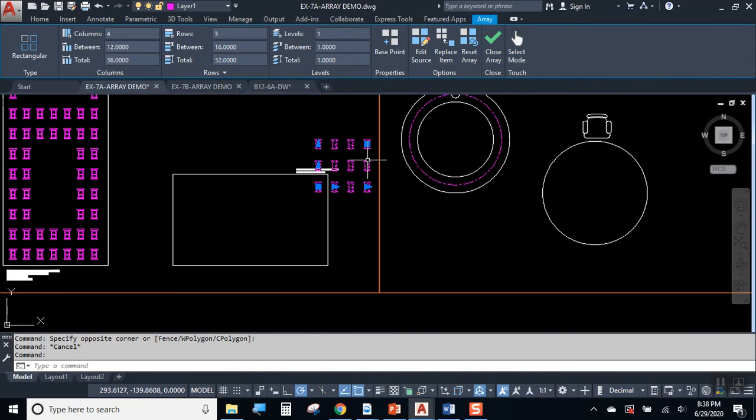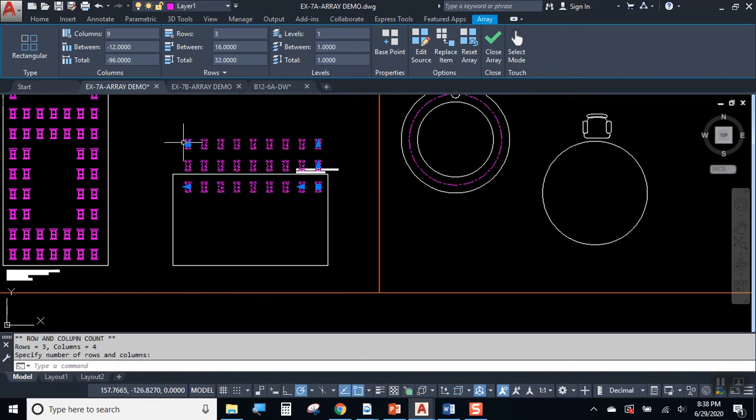Well, part of the reason is because of relative coordinates. You remember relative coordinates? It was so long ago, right? Relative coordinates say the values, if they are positive, go to the right in the x direction and up in the y direction. So if we want to go to the left, notice that now we have a negative value.